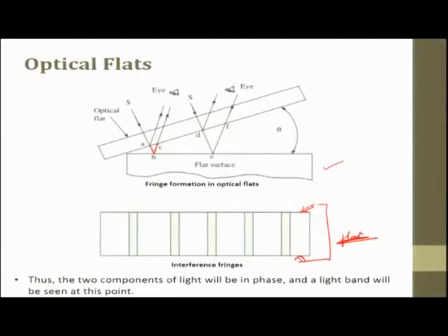So, what we are trying to say is, this is an optical flat, a flat surface. If you want to measure the flatness of a surface, we use an optical flat. Both the surfaces are flat and the light from the source falls on it. This reflects at A, reaches the workpiece, the flat bottom side, and goes. So, if we say this is lambda by 2 and this is 3 lambda by 2, then we have total interference happening. It is placed at a small angle theta.